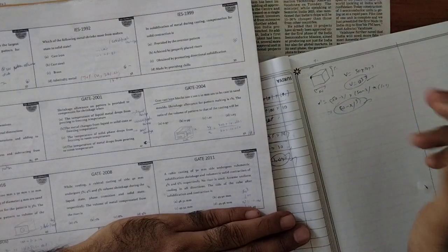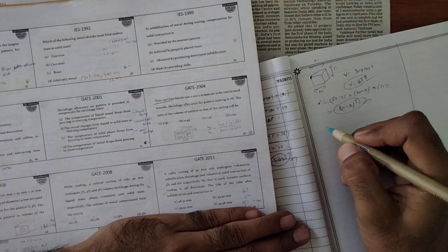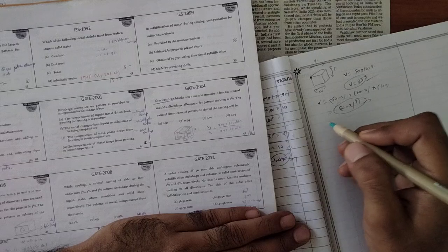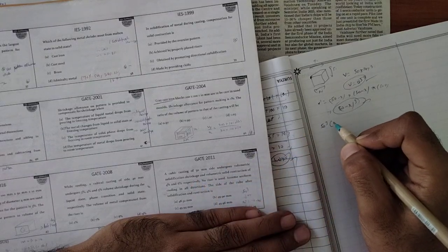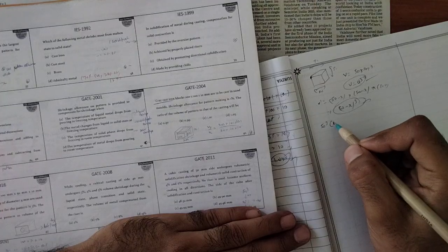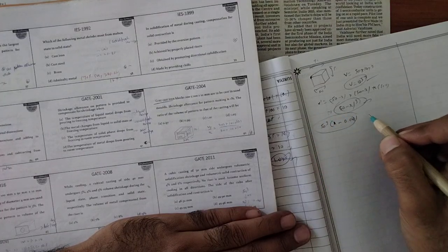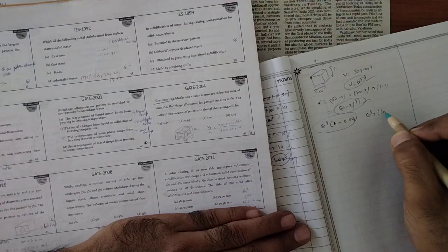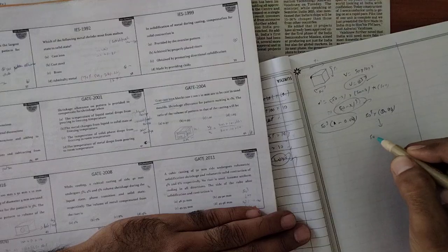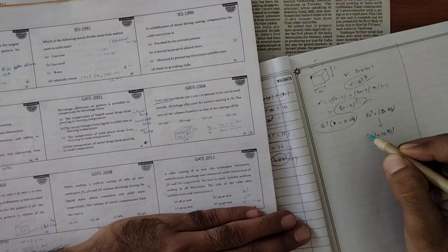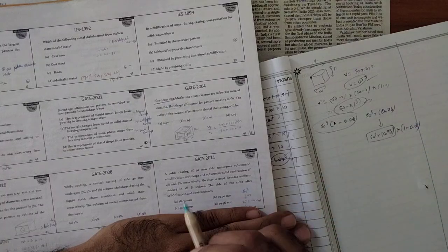Here shrinkage has been occurring twice. Okay, it means it's been reducing. One thing you can see here, the solidification shrinkage is 50 cubed. Since it's been shrinking, you can see 1 minus 0.04. So we'll take this answer: 50 the whole cube into 0.96. Next, again 50 the whole cube into 0.96, the entire thing into 1 minus 0.06. So this one is 6%.